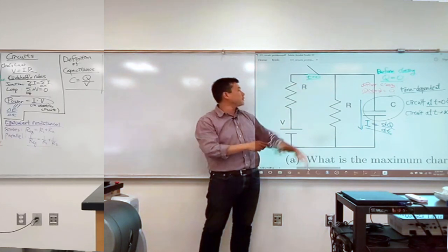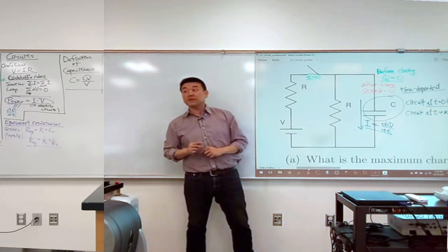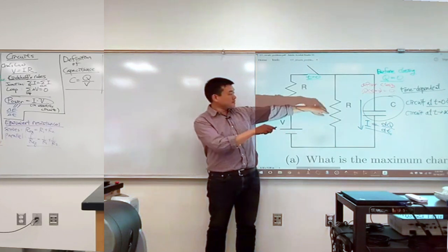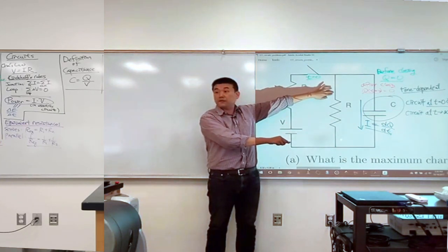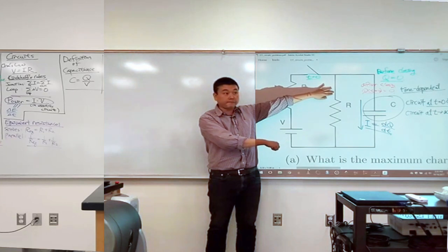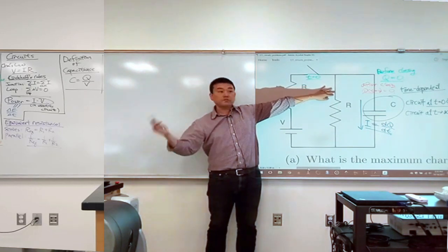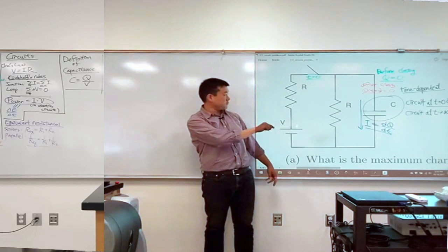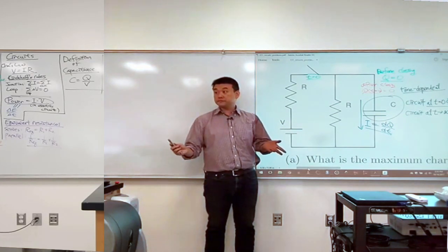I have no way of finding this directly. I want to get to something else that I can actually find out in a single step. There's something else that's equal to the voltage difference from one end of the resistor to the other end, some other voltage in this circuit. The voltage after the first resistor? Yeah, that's what I'm trying to get at. Is the voltage different to the battery? No, the voltage here is not going to be the same as the battery because there's this resistor here. If there's current flowing, the voltage will change.